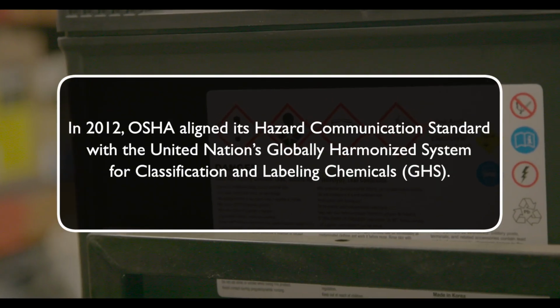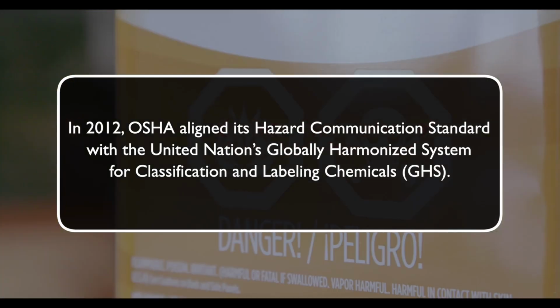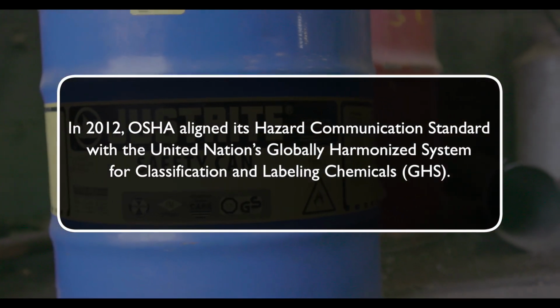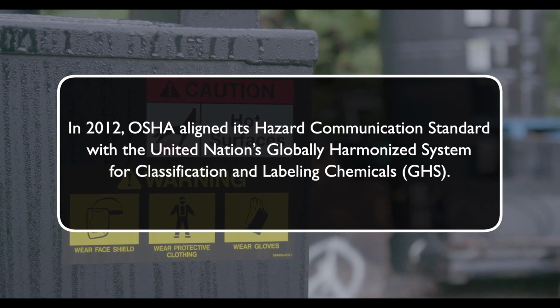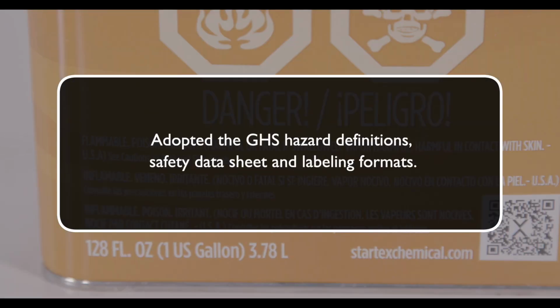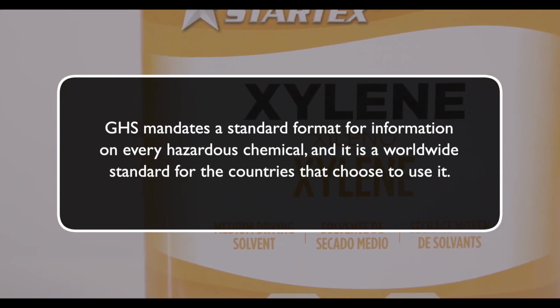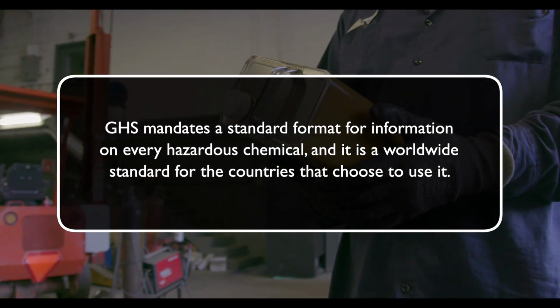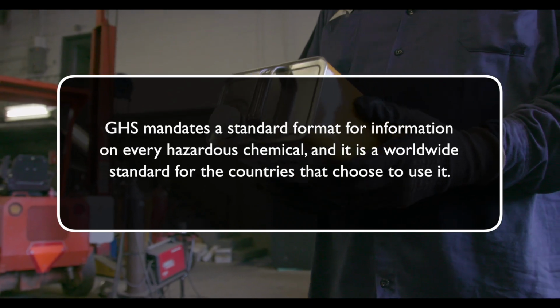In 2012, OSHA aligned its Hazard Communication Standard with the United Nations Globally Harmonized System for Classification and Labeling of Chemicals. While OSHA maintained the framework of its traditional HAZCOM standard, it adopted the GHS hazard definitions, safety data sheet, and labeling formats. GHS mandates a standard format for information on every hazardous chemical, and it is a worldwide standard for the countries that choose to use it.